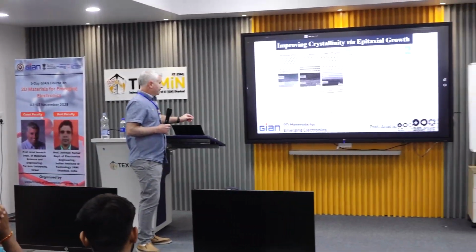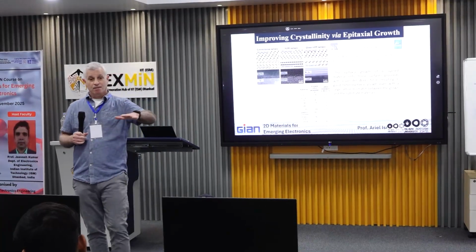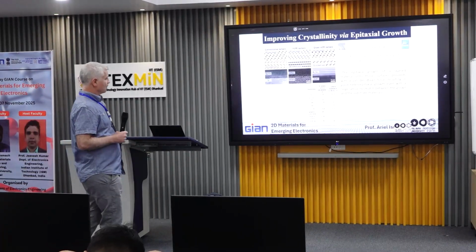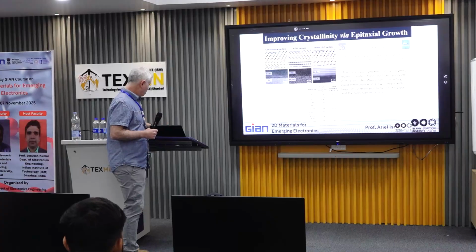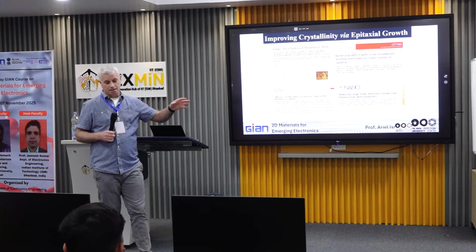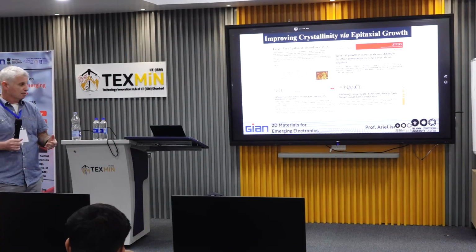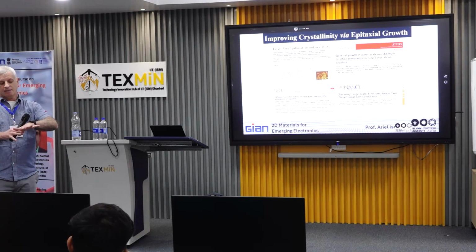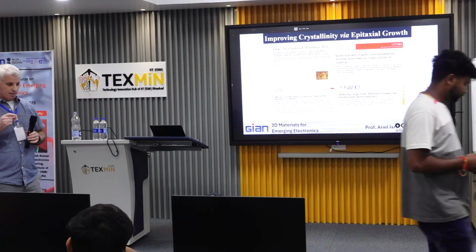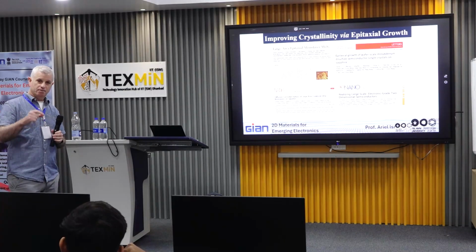Okay, so then you see that you get epitaxial growth even in large mismatches, right? Because of strain relaxation. But actually, the truth is more complicated, and the truth is that even in epitaxial growth with large mismatch, the system aligns itself in an attempt to reduce the lattice mismatch.